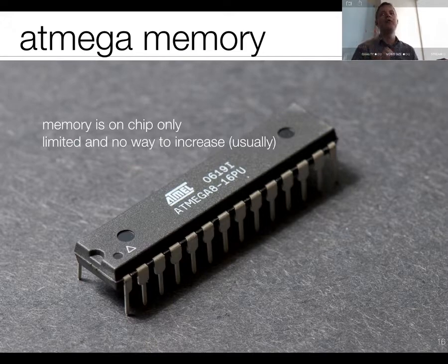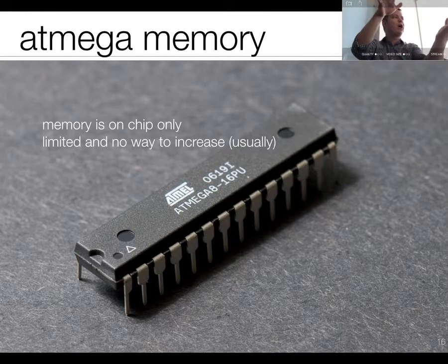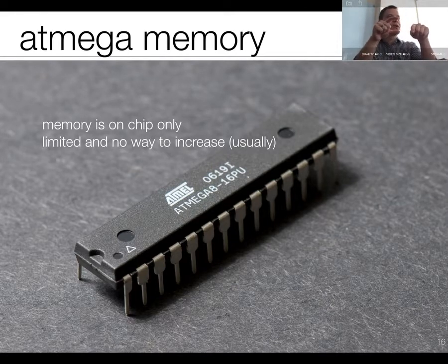Usually, there are some microcontrollers that have some dedicated pins on them for when you'd want to do SRAM access for an off-chip SRAM, right? So you could buy a chip that's SRAM, solder it down onto the board, and make sure the wires are connected, and then you set it up. Essentially, when you're loading up the program, you tell it which pins to go out on and read from the SRAM. That is not usually the way you want to do it with a microcontroller because it's a lot slower, and you have limited clock cycles anyway.